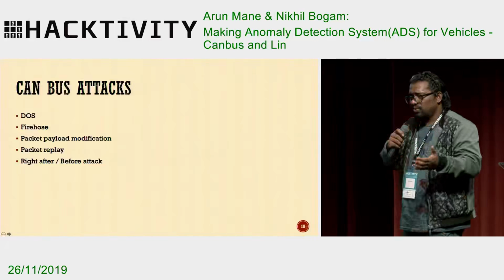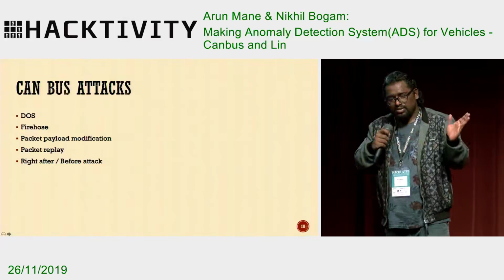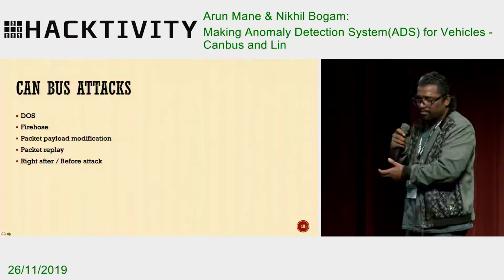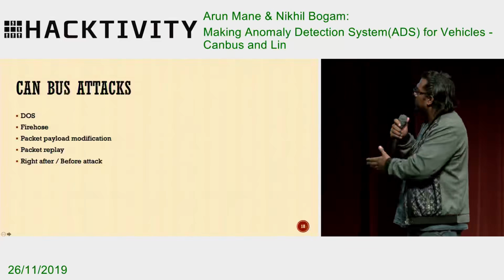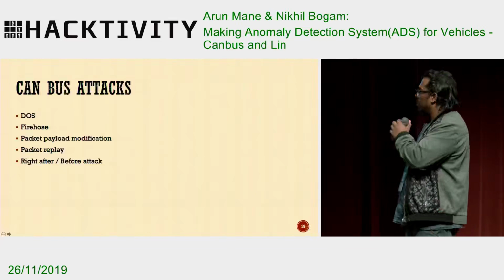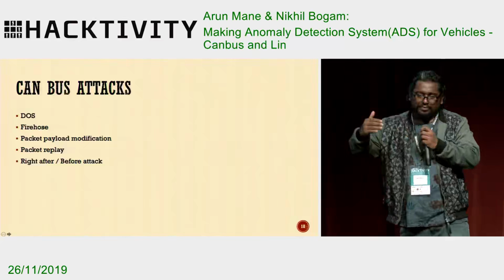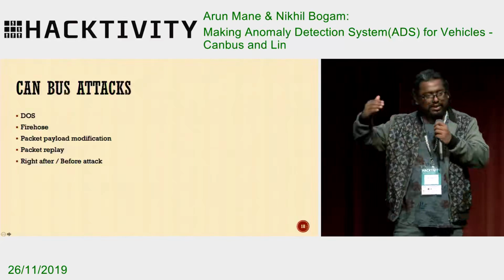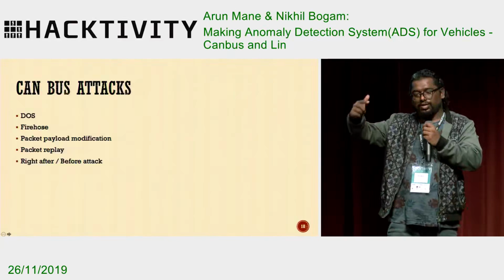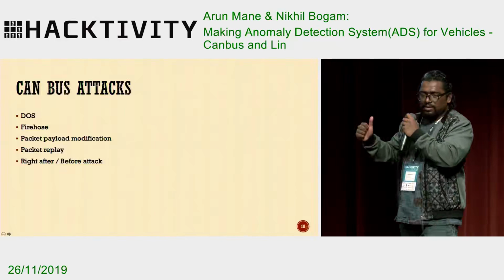So once you know the arbitration ID, and in the DLC, if you send all zeros, 8 bytes of zero data, it creates a DoS on that particular arbitration ID. These are the kind of attacks you can do. Fuzzing is nothing but once you sniff the entire communication, if you see the timestamp between two consecutive messages, it would always be small.